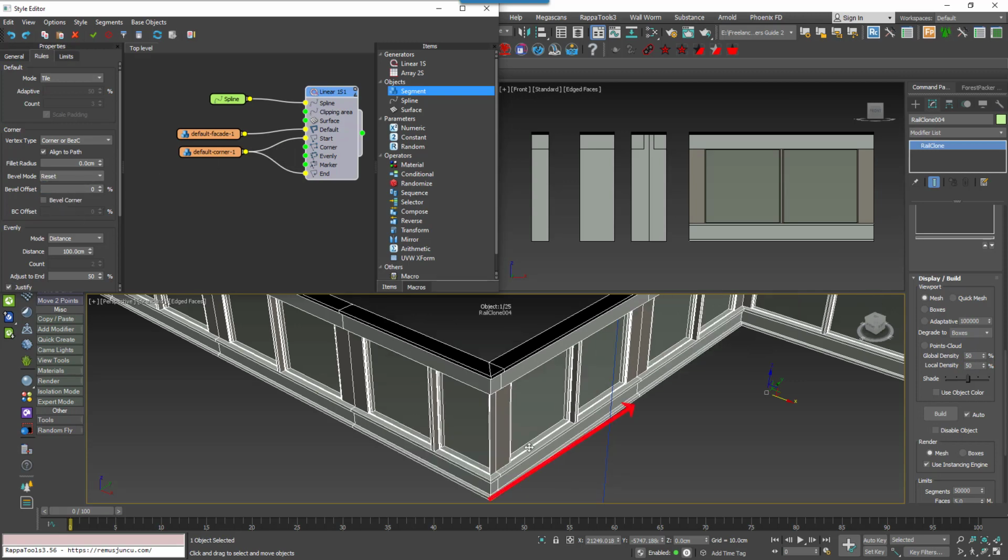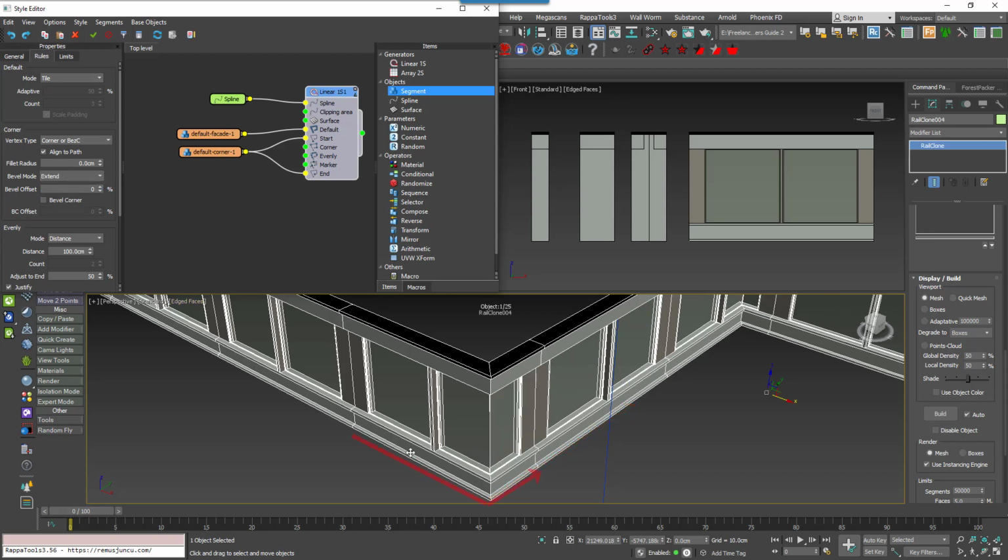Reset starts the geometry again, so you'll get a full width segment appear immediately after the corner. There's no attempt to wrap the segment around. Extend slices the geometry so that the length of the segment is maintained as though it continues around the corner, giving it an appearance of continuity. And finally, symmetric matches the size of the segment on both sides of the corner. So now we understand that, let's wire in a corner segment.